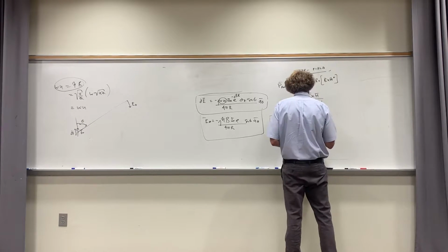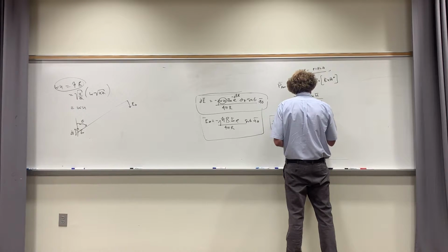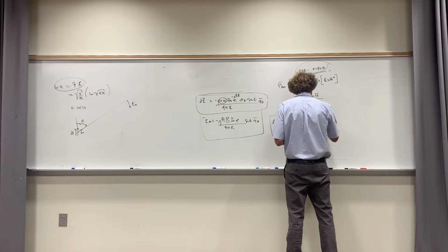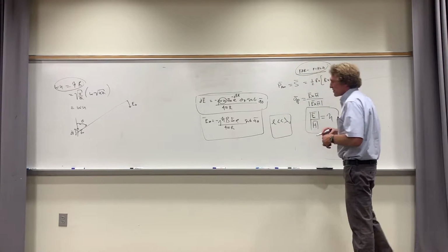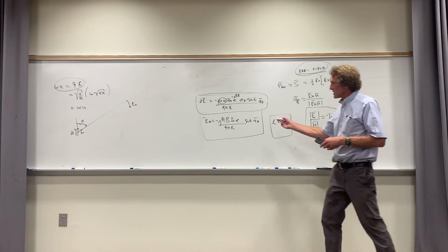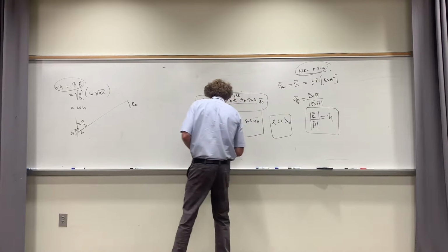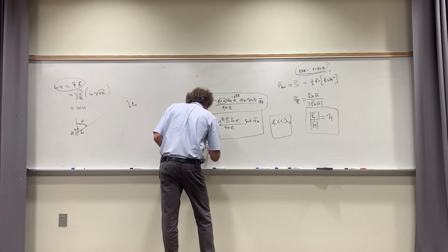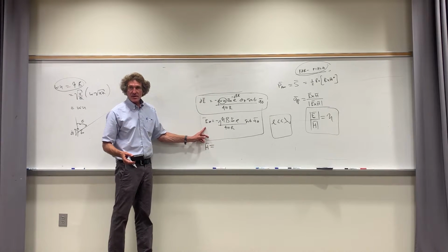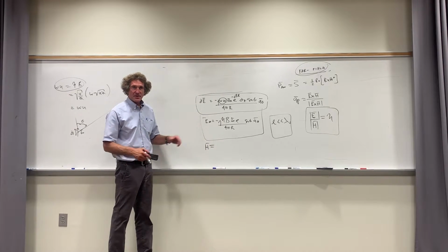It also means that the ratio of the electric field over the magnetic field, and this is all in the far field now, the magnitudes of this are equal to eta in the region. So, because of that, I can do something really nice. If I have the E field and I want the H field, the H field will be perpendicular to this and perpendicular to the direction of propagation.